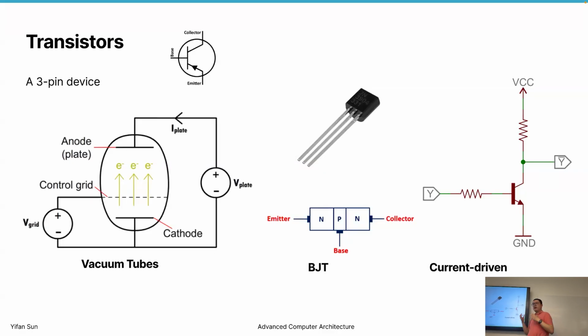And because we can only bring the heat away at a certain speed, we cannot generate heat too fast, right? If it's generating heat too fast, the temperature of the chip gets too high, above a certain degree, and then the chip will melt. So we have to turn off some cores or some part of the circuit so that we stay within the power limit.